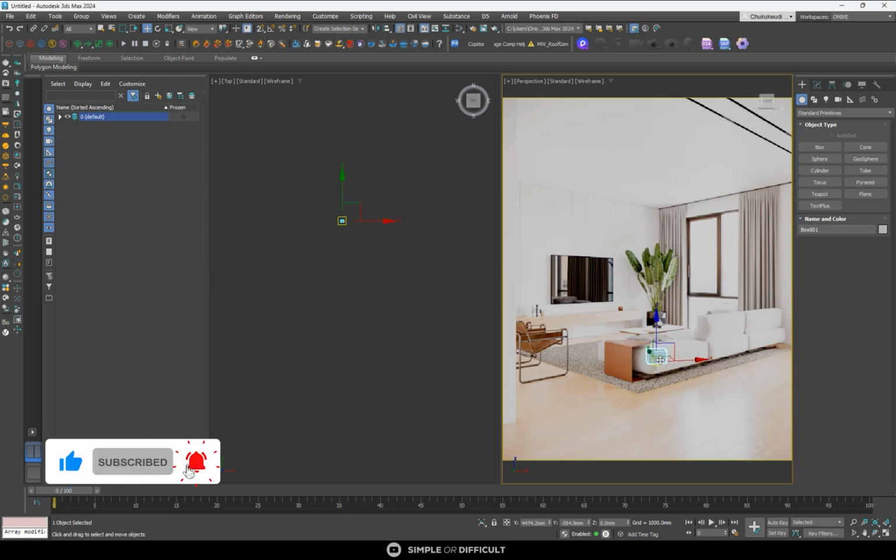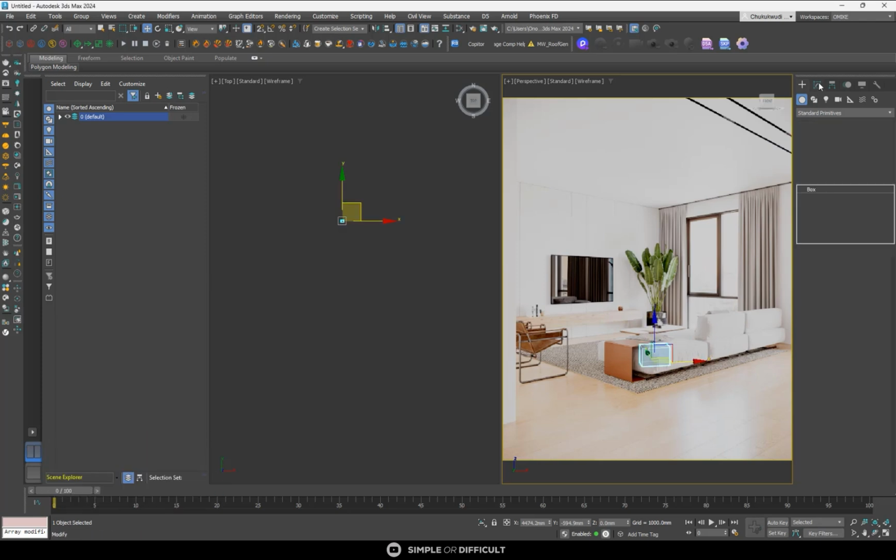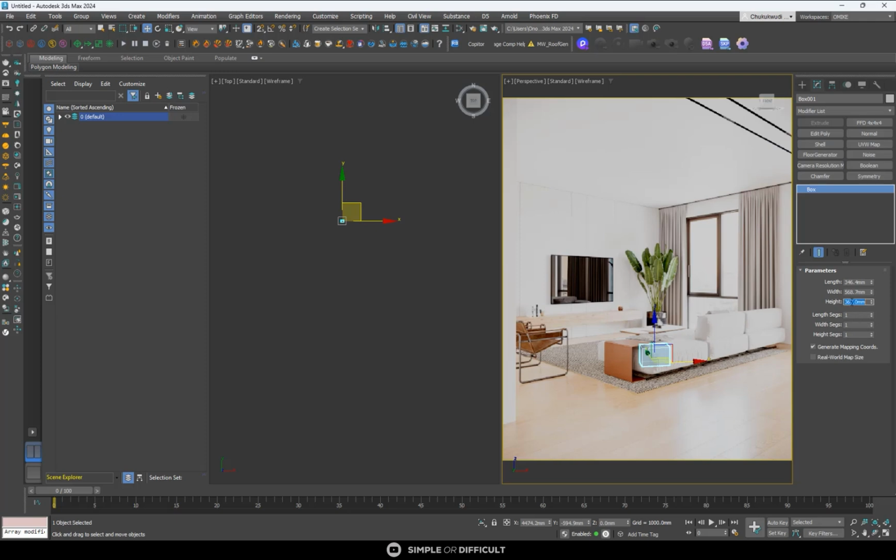And then I can use the scroll wheel to zoom in a little bit. But before I do that, I need to ensure that the height of this is 400, right? It doesn't really matter what these ones are. We're going to adjust those ones later when we get the right angle. Okay, so now the next thing I want us to do is to do perspective match, right? When we get the right perspective, then we can set our camera and then we can start modeling, right? Before, when we are modeling from the plan, usually what we do is we just model and then we set camera.